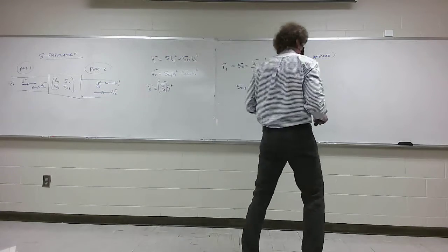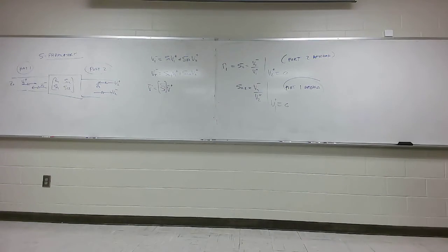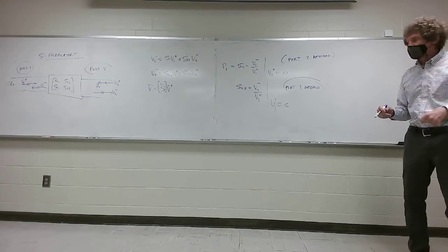All right. Now we get to S21 and S12. You all know what voltage gain is, right? When you had your microelectronics course, you calculated input versus, or output versus input voltage ratios, didn't you, class? That was considered the forward voltage gain. How many remember with transistors you also had reverse voltage gain? You remember that? Reverse voltage gain, both of which are important ideas to understand.